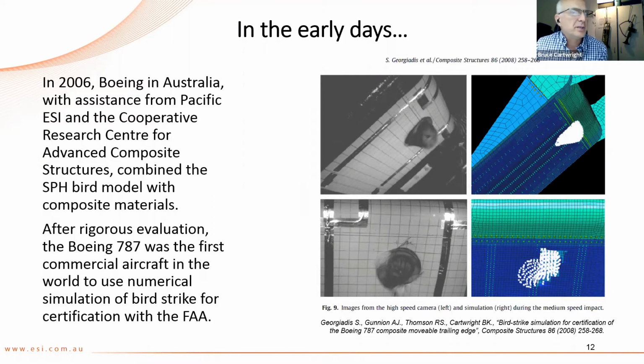It's also essential that we have the modeling of the composite materials at which they're being fired against calibrated as well. So these structures here are fully composite carbon epoxy structures with internal structures as well. And this whole process modeled the impact of the bird against the wing and the failure of the composites.